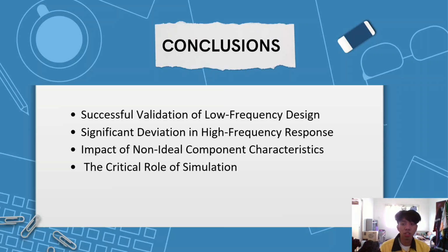So second conclusion is significant deviation in high frequency response. So a major discrepancy was discovered at the upper frequency limit. While the theoretical design calculated an upper cutoff at 300 kHz, the simulation revealed it dropping significantly to 34.3 kHz.